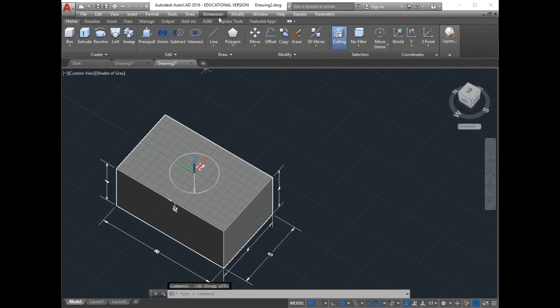And now I'm going to again put dimension and then radius. You pick up the circle. Wherever you put your mouse, it will be located. You got it, guys? Before, I was activating the 3D object snap, and I was also activating the center of the face. This is why wherever I put this center, it's as if it has a magnet, and it puts everything there.